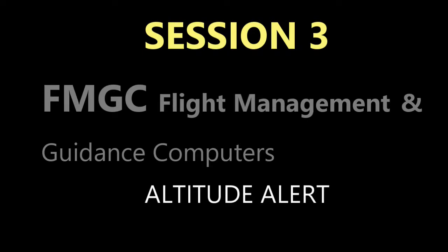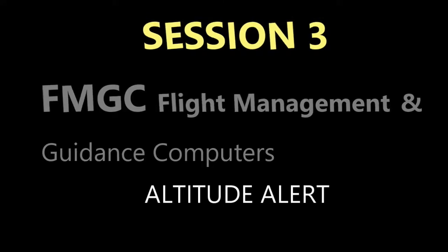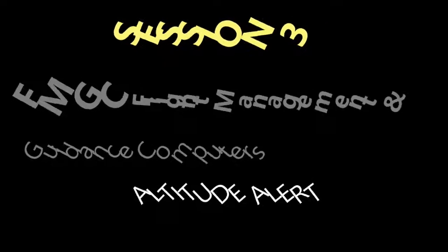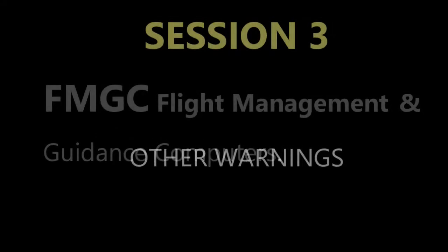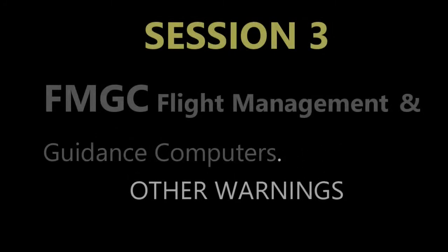So let's look at this a little bit. On decision height, this is one warning. Some of them have an aural warning, where you're actually hearing a voice. Remember I said there was one that said speed, speed, speed. That actually gets said, but it's just a voice warning, audio. So with the decision height warning, you have that synthetic voice warning if the decision height is within or going outside of threshold. This all depends on the radio altitude along with the decision height.